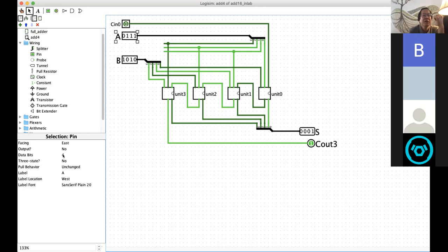Let's check a few values here. Is there any of these values that's different from what I'm showing here? Oh, I didn't realize the output had to be set to no. Ah, there you go. You have an output pin there, that's why it says X. Now, output pins don't have memory for this particular setup. So if you have nothing driving an output pin, it will say X. Okay.